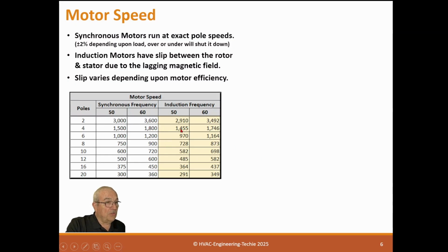Now, we used to use this a lot. If we needed a 700 RPM motor, we'd go to a 10-pole motor, and we'd be turning around 700 RPM, which is how we got motors to run lower. I never actually have had one over 10 poles. I guess they made them, but I certainly never had to use one. Nowadays, of course, you'd buy a 4-pole motor and use a VFD and slow it down to anything you want. And that's a little more efficient way to do it.